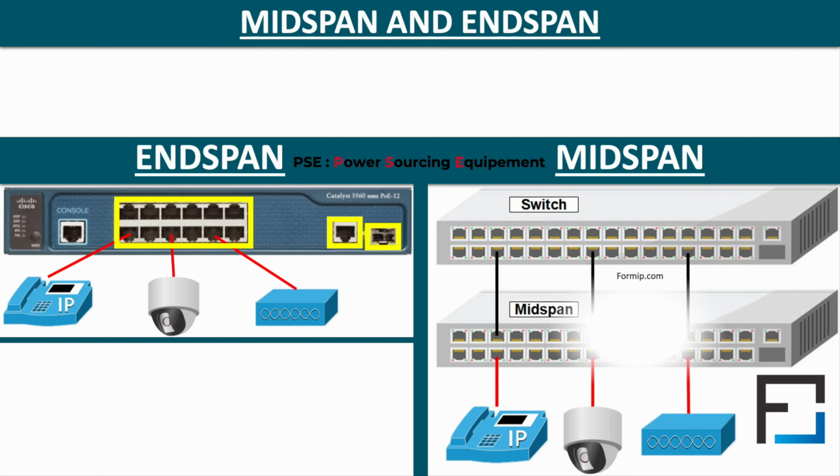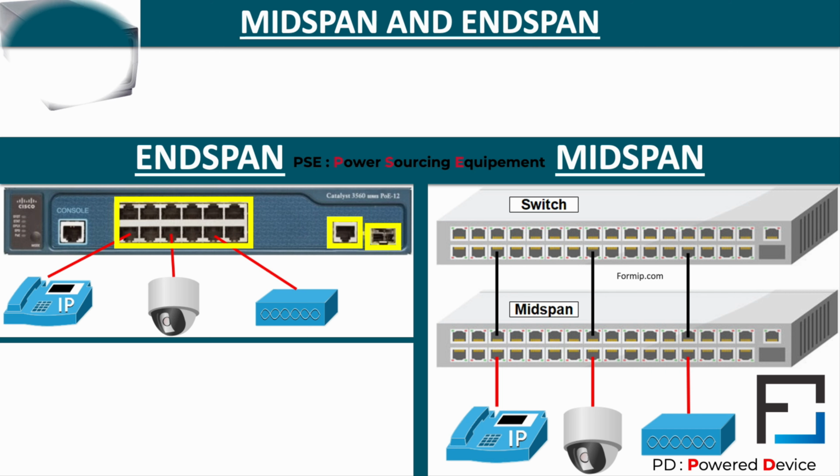The other power method is the mid-span PoE method, which allows PoE technology to be added without having to replace your own non-PoE switches. They are smart devices, and, like a PoE switch, they also allow you to detect if the powered device, PD, needs power. This type of device is very useful if you have very little equipment to power. PoE injectors are useful when you only have a few devices to power. There are even small PoE injectors, which can be used to power only one device.